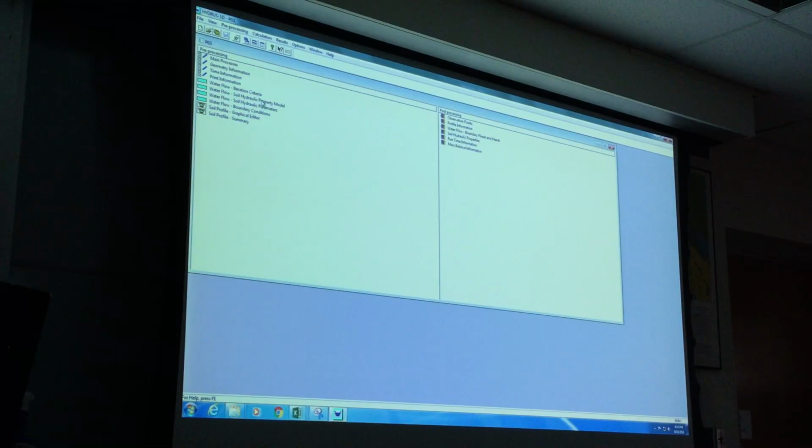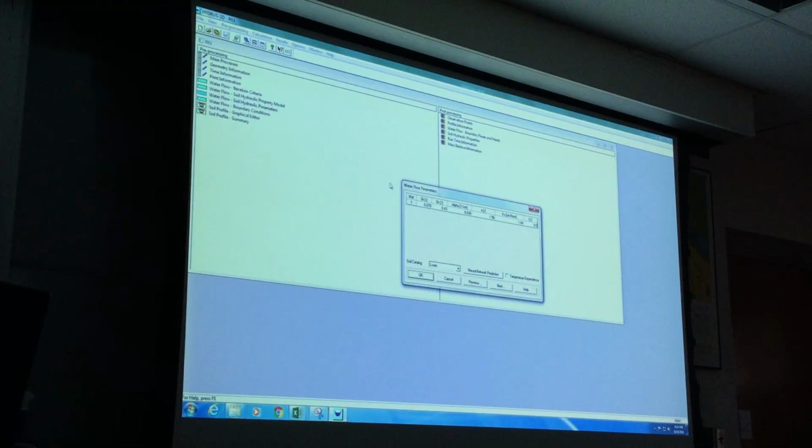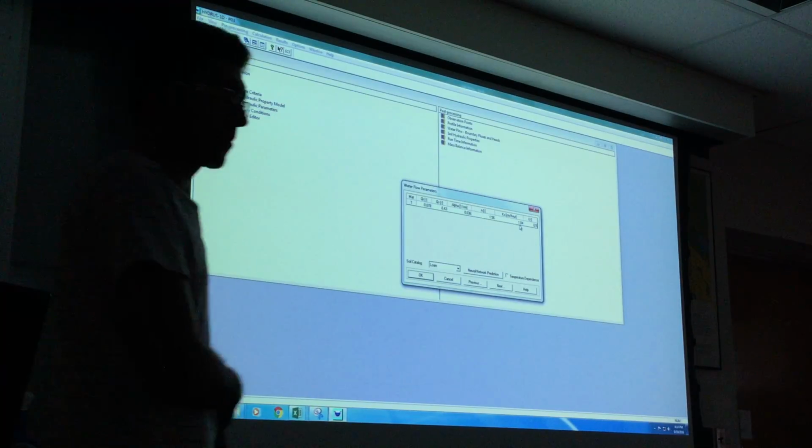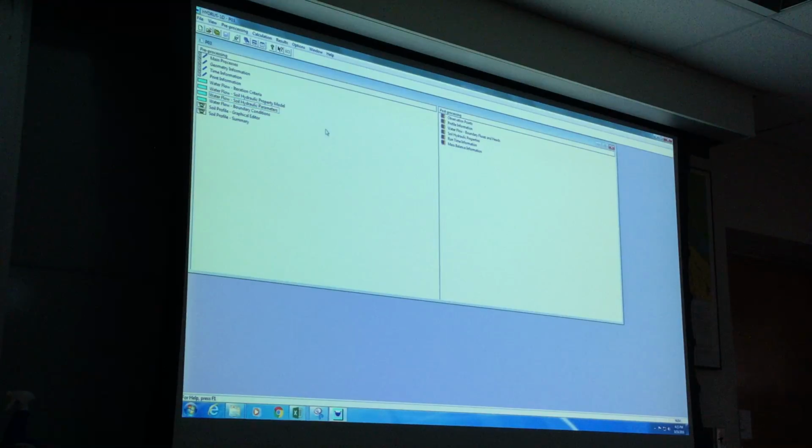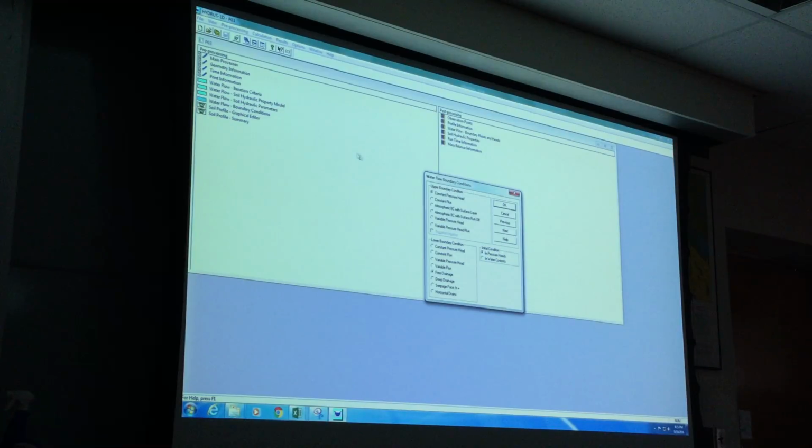So now when we go to soil hydraulic parameters, you basically see that the saturated hydraulic conductivity is 1.04 for loam. And this is exactly the flux that we want to apply, that we want to force onto the system on the top. So the only thing we actually want to change is the boundary condition.